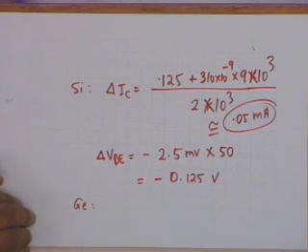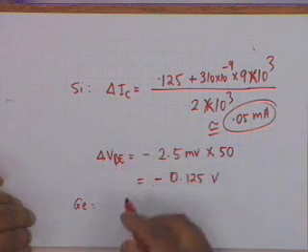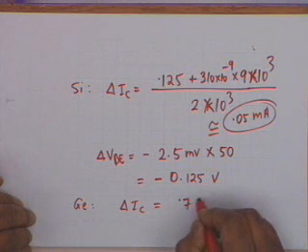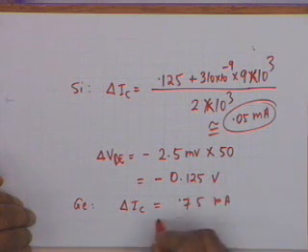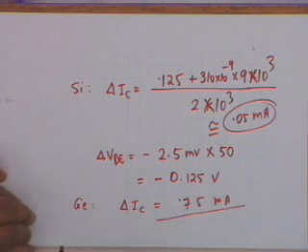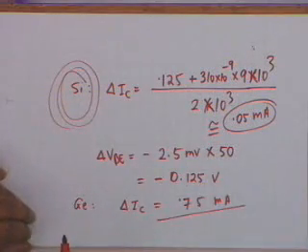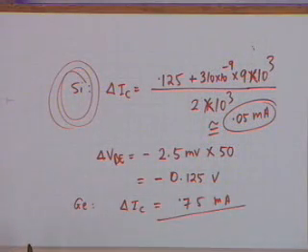If you put that, delta I sub C calculates out to 0.75 milliampere, and you see the range of variation. Whereas this is only 0.05, germanium, same rise of temperature can cause a large change in I sub C, and this is the reason why silicon is always preferred, particularly where the device has to work under extreme temperature conditions. All right.